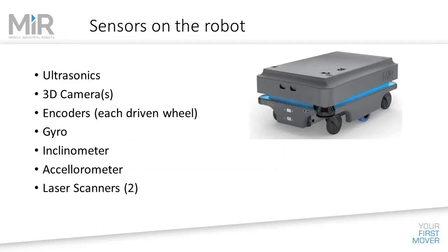The sensors on board the robot, there are ultrasonic sensors. Those sensors are right here. They assist the robot if you're coming up perhaps on a glass wall. You've got glass doorways, so it doesn't run into those glass doorways. The lasers may or may not bounce back accurately off those glass doors, so there's some ultrasonics built into the front. The 3D camera we talked about when we had the lid off of it. These 2 apertures right here are where the 3D camera is looking through that cowl.